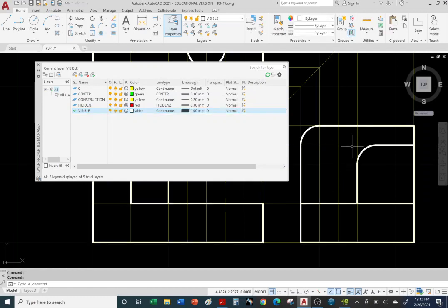You can see the line thickness change. All right, so all these line weights, when you go work for a company, they should already have a template set up with the layers and the line thicknesses and the colors. I chose these colors, so later on, the second half of the semester, you'll be creating your own layers, your own colors, your own line types and line weights.